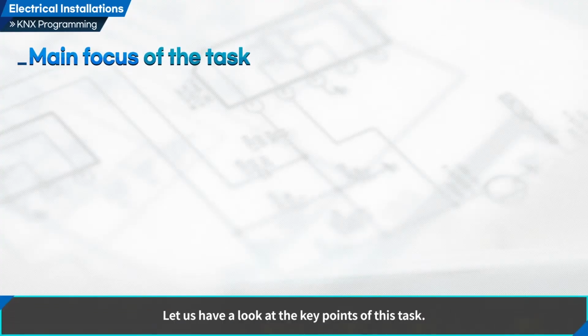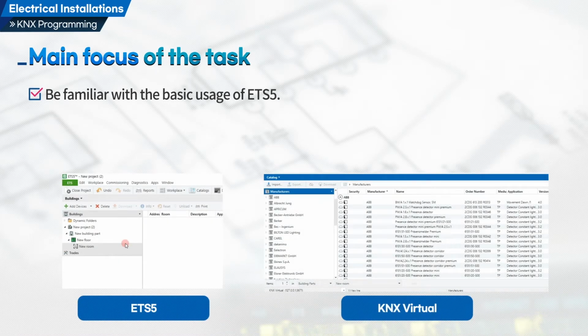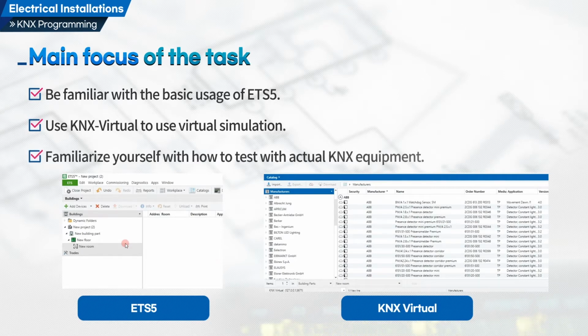Let us have a look at the key points of this task. First, be familiar with the basic usage of ETS5. Second, use KNX Virtual to use virtual simulation. Third, familiarize yourself with how to test with actual KNX equipment.